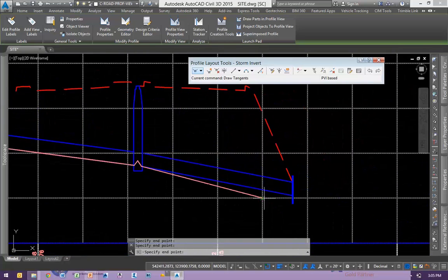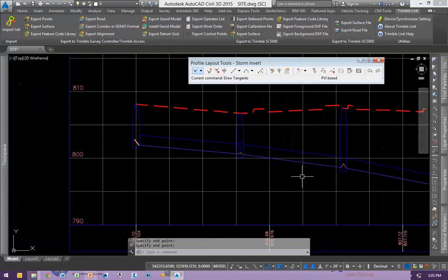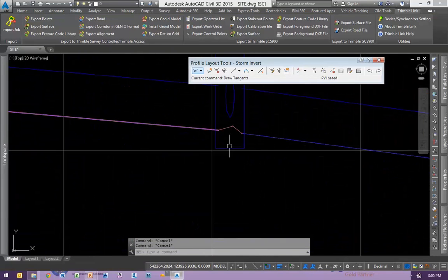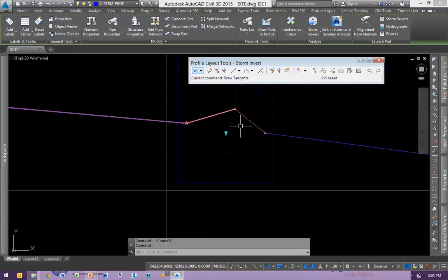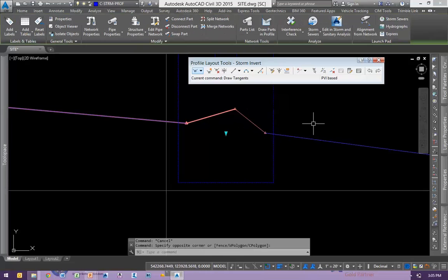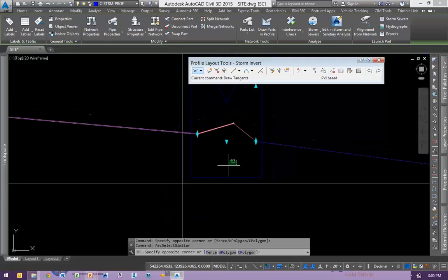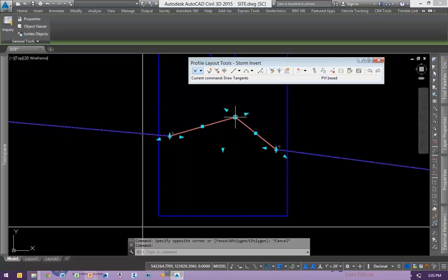So once I do this, if you guys have some suggestions, once I explain what I'm doing, definitely open to it. This right here is the bottom of the structure floor. Invert is right there. There's no way to snap to that in an easy way. I can't turn that on. So what I find is the easiest for me to do, turn these structures on like this. Just grab this and do the magnetic snapping like this.